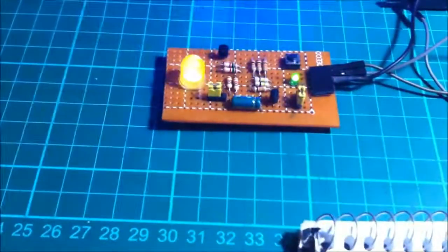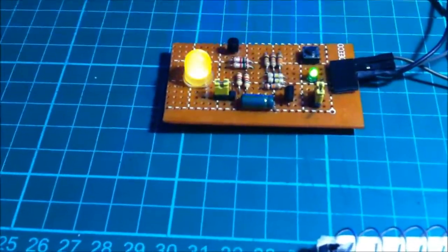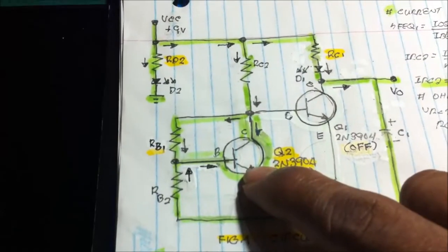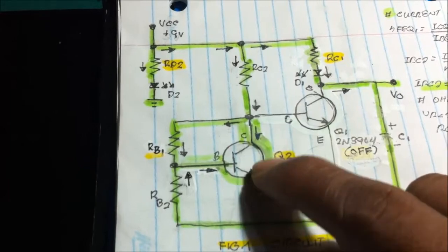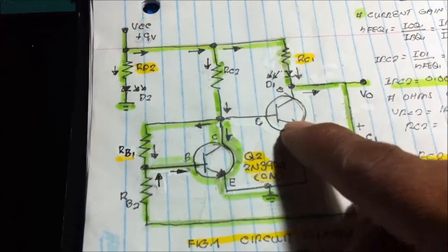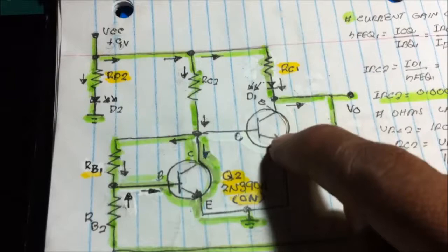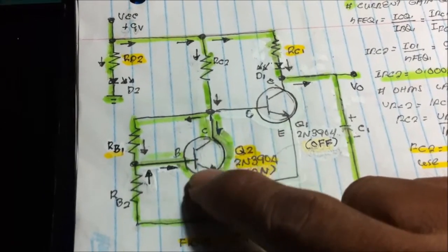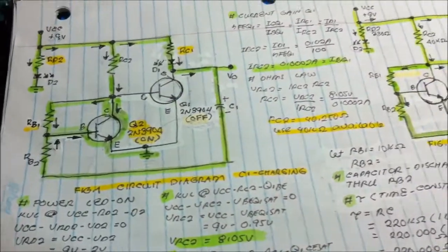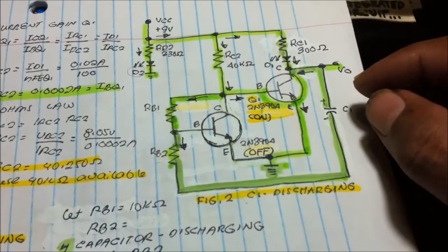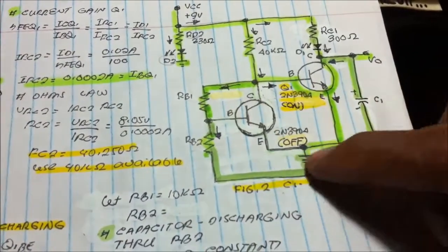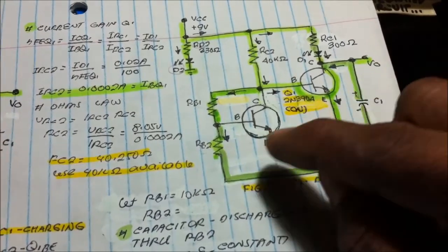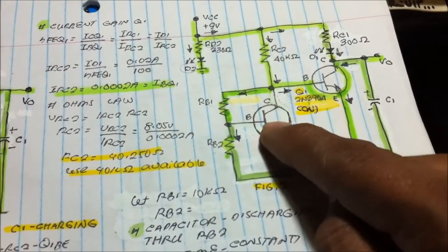That's why we have this LED flasher switchboard, because this transistor is serving as a switch to this transistor. This is the transistor carrying the load. This is the load side, this is the switch side, the input side. So we now know why it is blinking, because of this circuitry: capacitor, resistor, and the transistor.